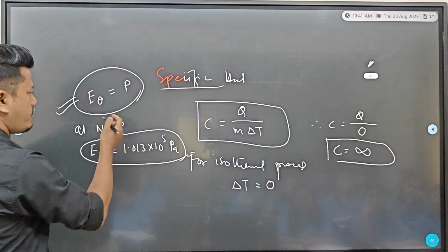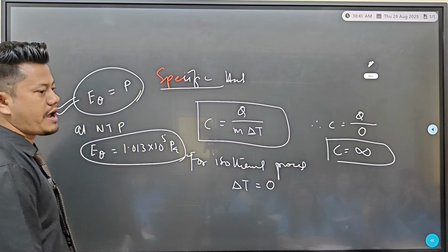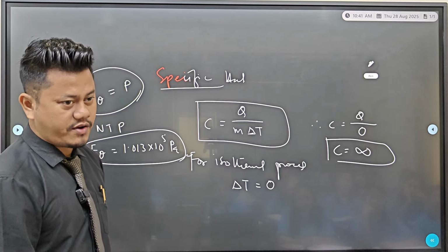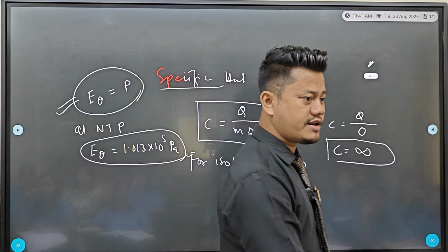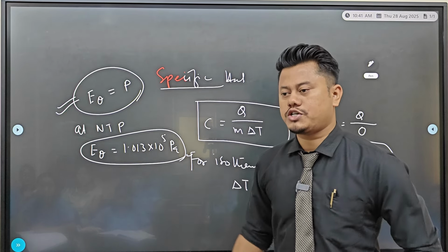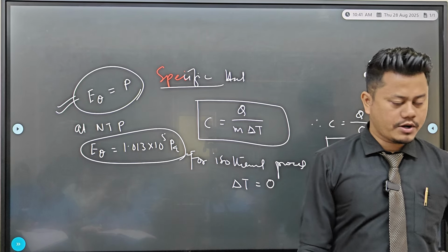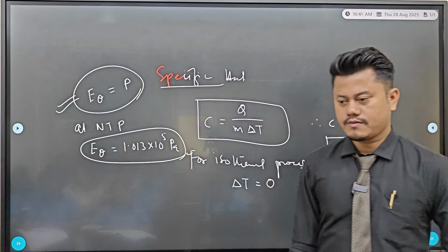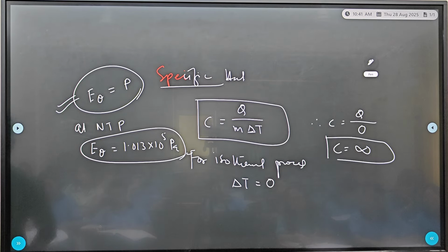And we came to know that isothermal elasticity is always given by pressure of the gas. Now at normal temperature and pressure it will be always atmospheric pressure, right? So isothermal elasticity will always take the value 1.013 into 10 to the power 5 Pascal. Please go for the next interpretation. Just put a star mark below and write this. Very easy, okay? Easy or not?